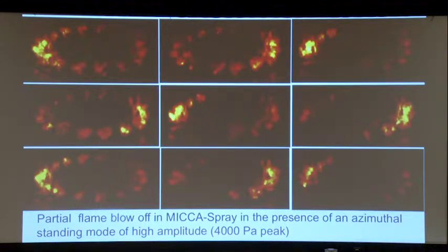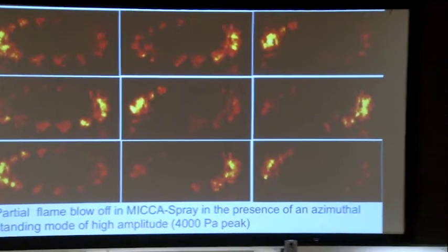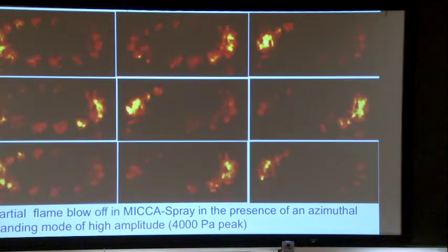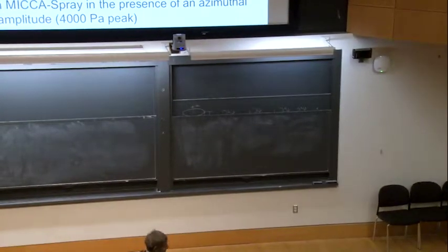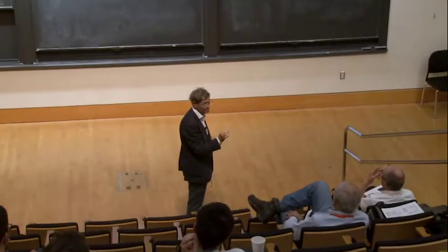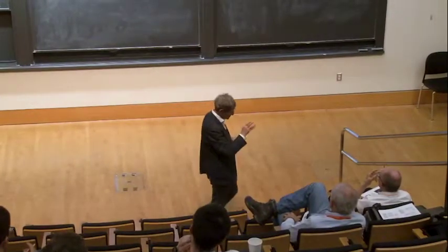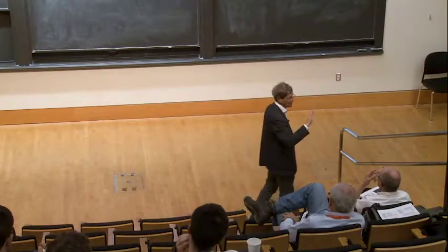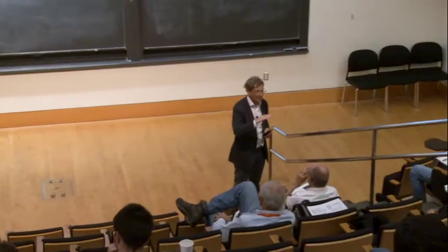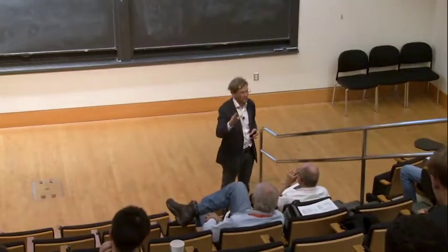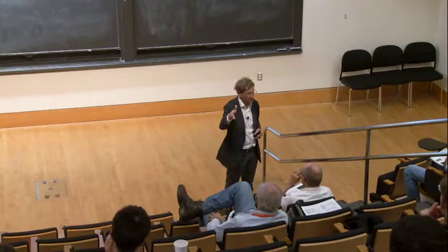Yes? Sorry? The cluster you have is essentially symmetrical. Yes, everything is symmetrical. What determines the direction of the nodal line? The nodal line. That's a big question, not yet fully answered. Why do we get standing modes? Why do we get spinning modes? We have some answers.